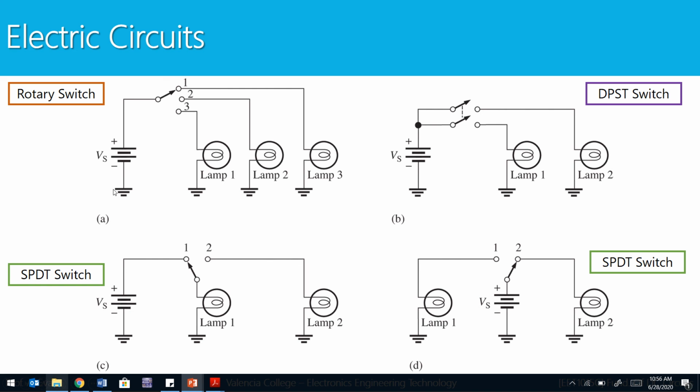So ground is going to be a very important part in this course. You're going to need to make sure when you draw or label circuits, you always have a ground. You have to have that reference point and that common return path.